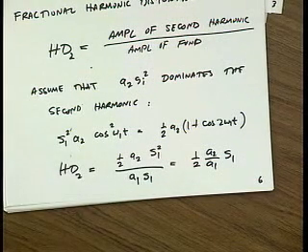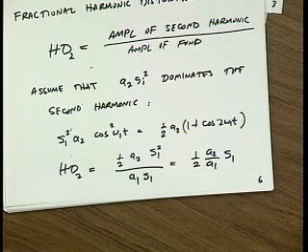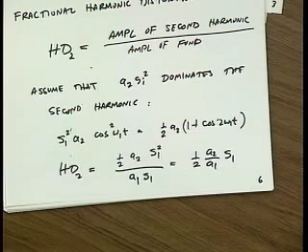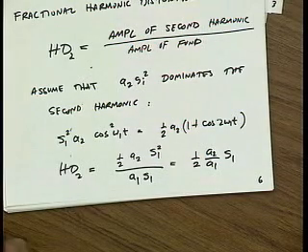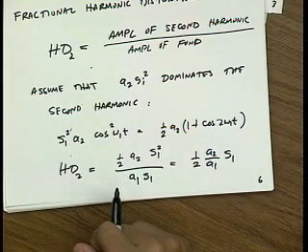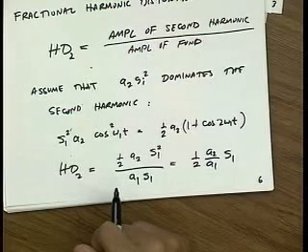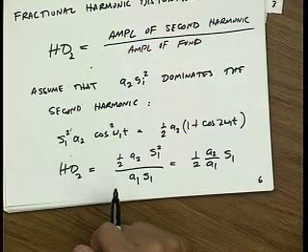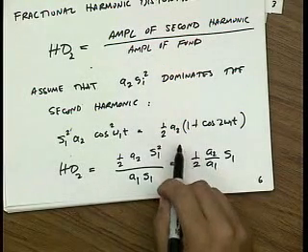Why should the second harmonic be of concern if it does not generate an in-band frequency component? The second harmonic is of concern because, first of all, it's generating distortion in someone else's band. Might not be your band, but someone else exists at second harmonic. Secondly, because it generates DC.